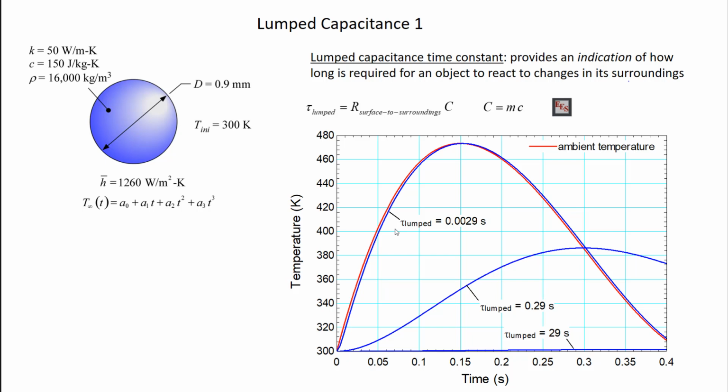In steady state problems, we had resistances. In transient problems, we have time constants, and this is one of two time constants that are really important. Okay, so we have this time constant, I know kind of what should happen. I have calculated the Biot number, so I know how I can simplify my problem. So the next thing to do is solve it.